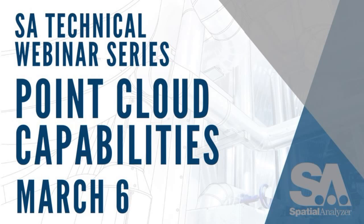From our CAD, we're going to go to Extract Nominal from CAD, and for data association, we'll hit this drop down and use Proximity Filtered Clouds. So it's going to use any clouds in a certain proximity to those CAD faces and assign them to that relationship. So from there, I'll go ahead and just hit cylinder.